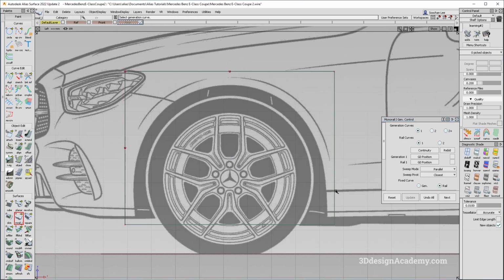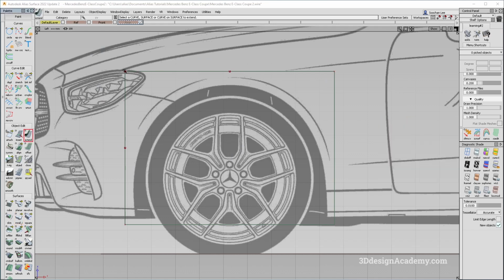It looks like this is a little bit too close to the end. So what I'm going to do is extend this one by, actually not by 1 mil. I'm going to extend this a little bit more by, let's say 5 mils over here. And actually let's do more than that. Okay, I'm going to say 15 mils, and extend 15 mils. You can just type it in like that. So that's a little bit bigger.